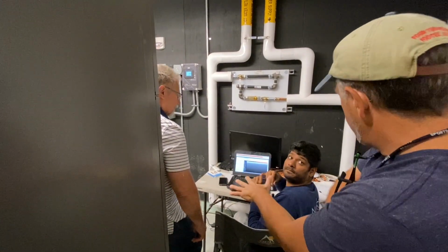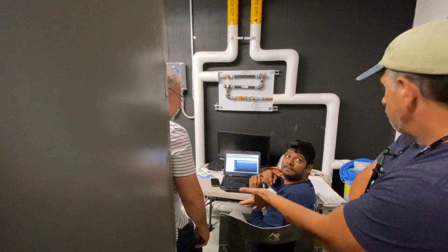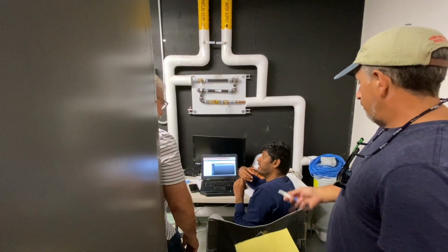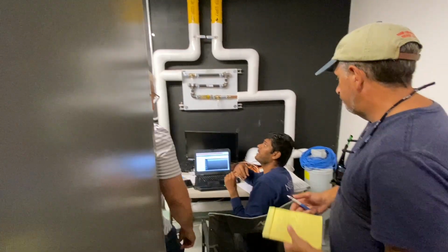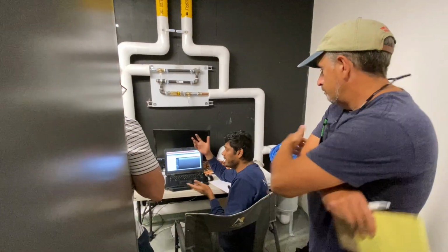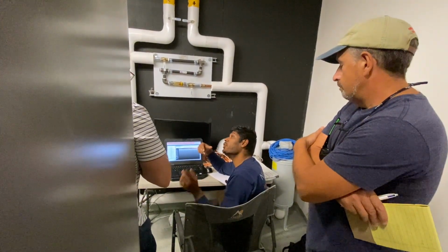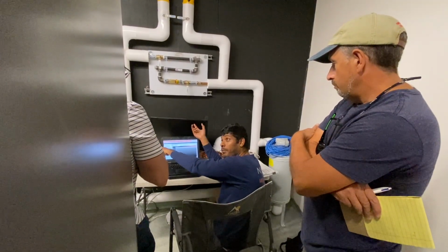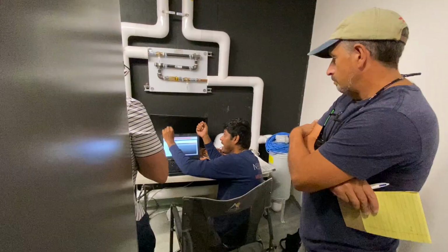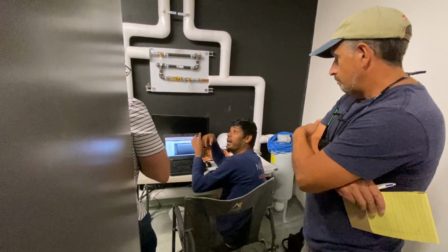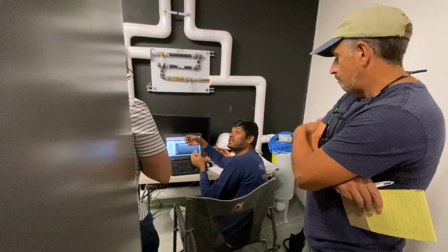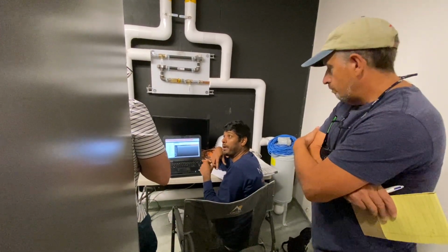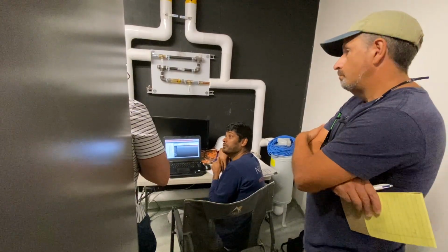That lighting portion, is that only during the occupied hours, or at any time? Anytime. So if somebody comes in here at 11 o'clock at night, what happens? Your schedule will be unoccupied, so if somebody comes late at night, it goes to bypass mode. It's what happens when you push an override button. It is unoccupied, but someone comes during the unoccupied time and pushes that button, so it goes to bypass mode, which is basically occupied mode. The same thing happens with the occupancy sensor. If someone comes during the unoccupied time, that goes to bypass mode.